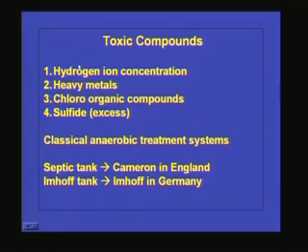So, we will see what we have discussed today. We were discussing what an anaerobic process is and how it is different from the aerobic process, and we have seen the advantages of the anaerobic process: it is less energy intensive and the sludge production is less, etc. But we have also seen the disadvantages of this anaerobic process, and because of those disadvantages, the anaerobic process was not popular till the recent past.